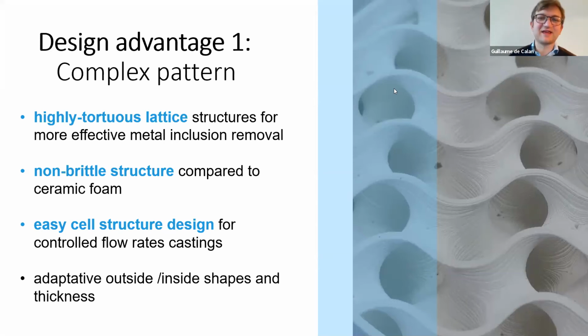Shrinkage doesn't change for X, Y, Z. So there's no simple answer to that. Hello, Federica, by the way. For ceramics, we usually consider that if there is a change, it is very small. It's not a very significant amount of change. If you do very big parts, you may check, but we usually give one oversizing factor, and that's it. For metal, it's different. For metal, there's a different shrinkage in X, Y, and Z. And we give two different shrinkage values in that case.